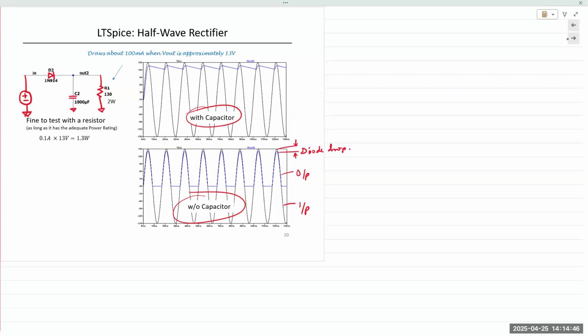And then you attach a capacitor and you simulate the same thing. You can see here, and I would encourage you to actually perform this simulation, the charging cycle. There is a difference, right? Because it's not charging to the peak. The diode is going to drop 0.6 to 0.7 volts across it. Plus, if you notice, the capacitor does not follow the waveform exactly as it is. If you zoom in here, you can see the peak of the waveform and then the charging of the capacitor.